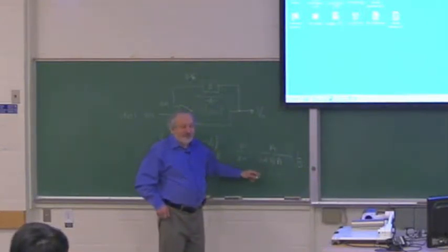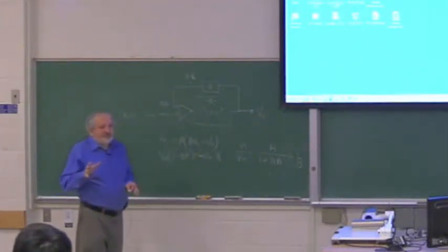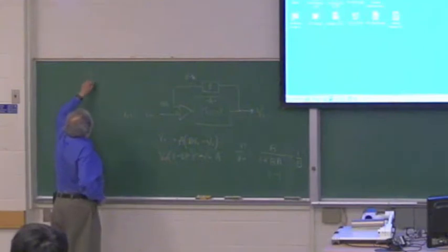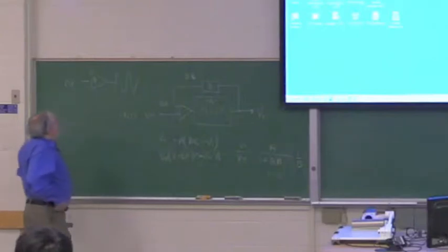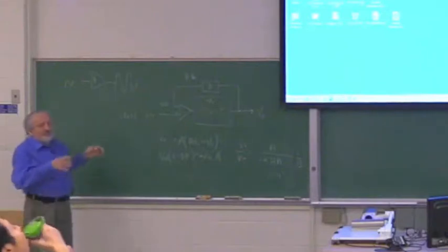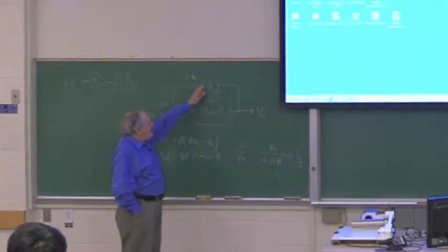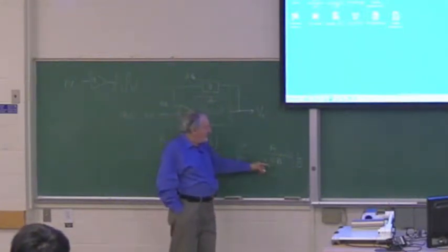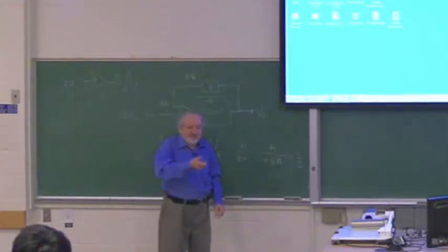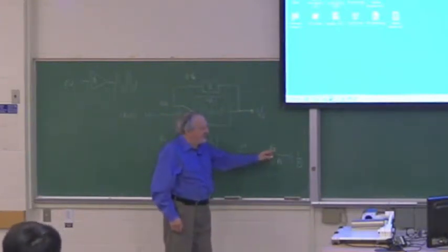Okay? So if you have an open loop system which is just a gain of A, it can never run to infinity. If you have an amplifier with a gain of A, you put in a signal, you get a big signal. If the gain is very big, you get a very big signal, but you couldn't have a situation where it will run away and go to infinity or start oscillating. But if you have a feedback system, and there is phase shift here, that BA can become negative, because if the phase shift is too big, it reverses the phase of the feedback, and again we'll discuss it a bit later. So this can become 0, the thing can run to infinity.